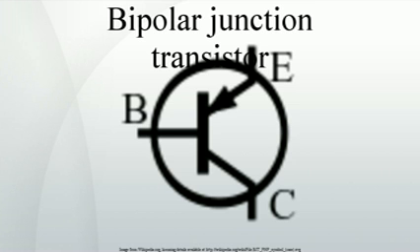The emitter current is related to VBE exponentially. At room temperature, an increase in VBE by approximately 60 mV increases the emitter current by a factor of 10. Because the base current is approximately proportional to the collector and emitter currents, they vary in the same way.